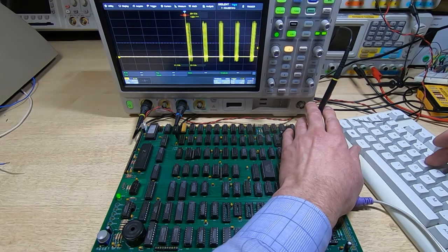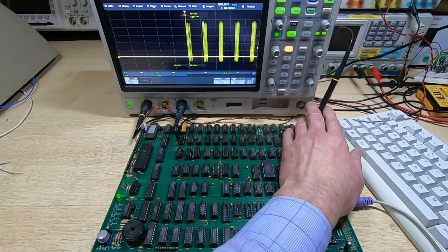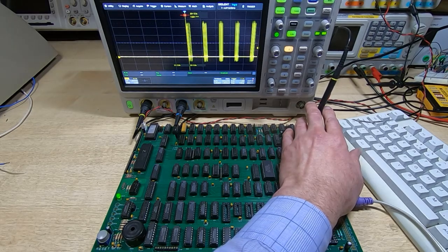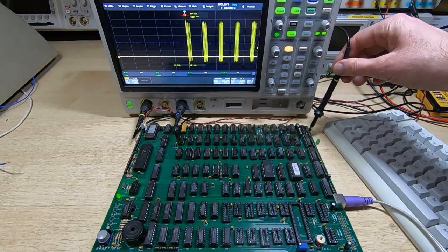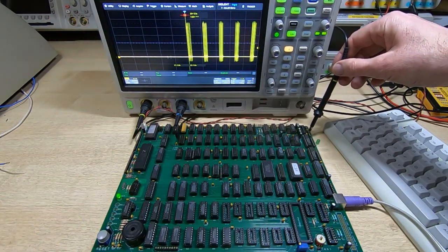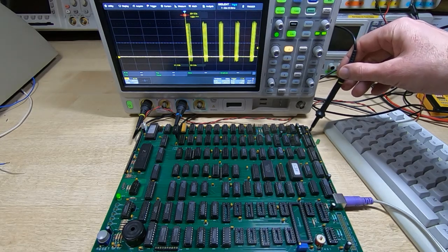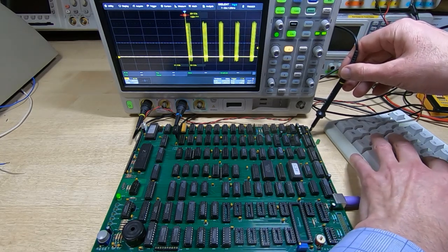So what we should see on the screen is a lot more activity, because it fills the SRAM that supplies data to the video with a character which will fill everything, so the entire scope display should be continuous data. But also the LED should come back on because we're running a self-test. So let's try this, fingers crossed.